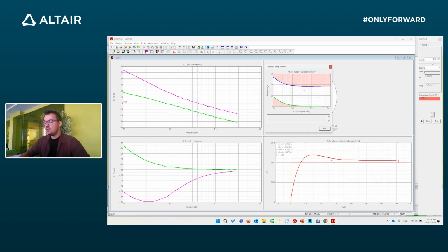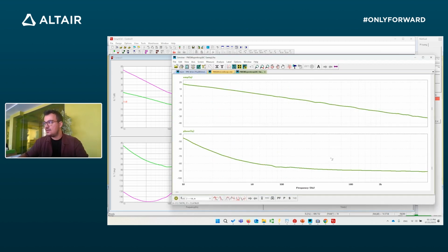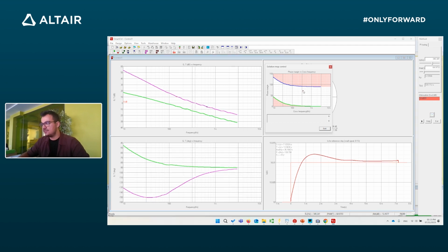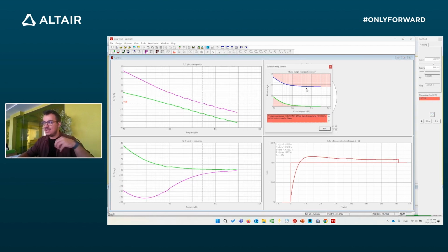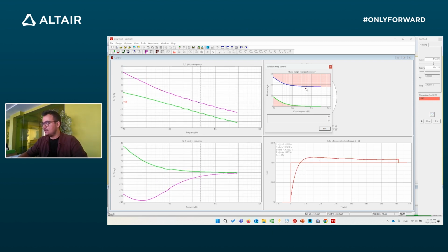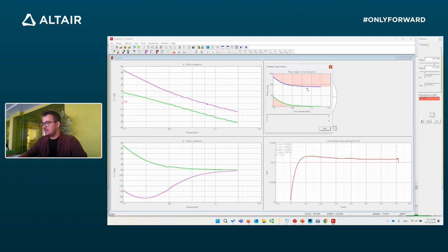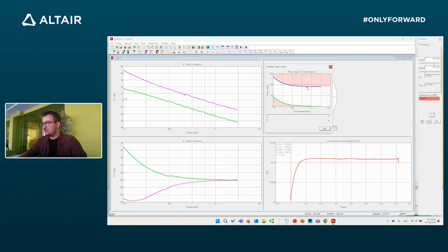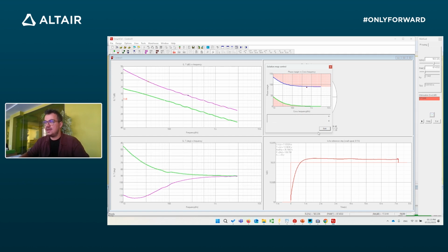On the bottom right, we see how the actual IQ transient waveform will look. Oh, and this is the result from the simulation. So it doesn't take that long for the AC sweep. But yeah, this is the IQ transient response, and we can modify the crossover frequency and phase margin to make it fast enough, but also stable, right? We want to hit a good stability point. Let's say somewhere, I don't know, maybe around here would be nice.